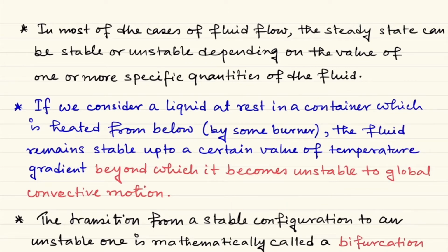So, what is a convective flow? Convective flow means a vertically up and down flow. The fluid at the bottom which is getting heated becomes lighter, so it flows up, and the fluid on the upper side, which is less heated because the heat source is at the bottom, is heavier, so it comes down to fill the empty part at the lower level.